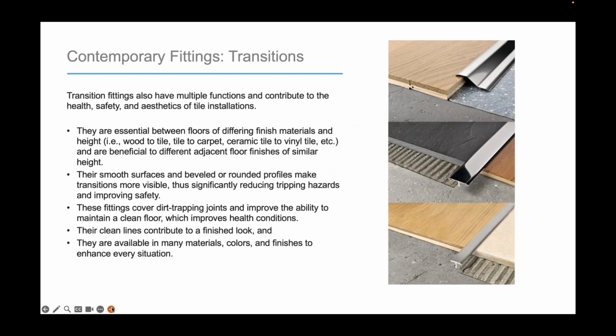And we also have different flooring transitions. The transition fittings have multiple functions that contribute to health, safety, and aesthetics of tile installations. They are essential between floors and differing finished materials, like wood to tile, tile to carpet, vinyl, and such. Their smooth surfaces are beveled or rounded. Profiles make transitions more visible, thus significantly reducing tripping hazards and improving safety.